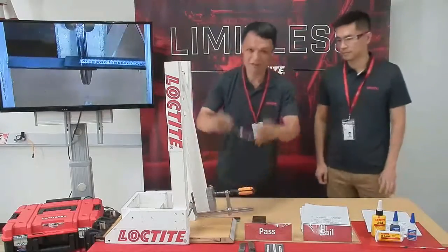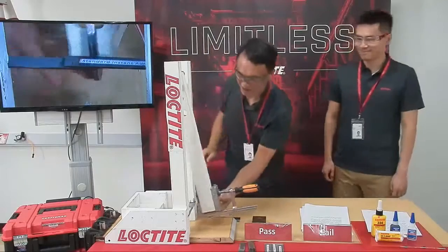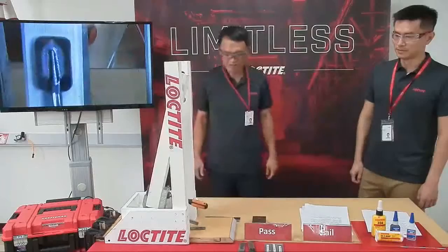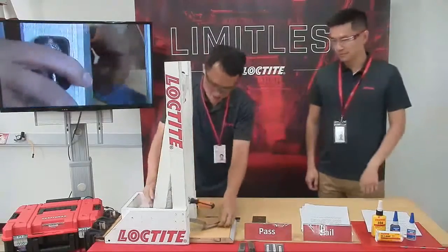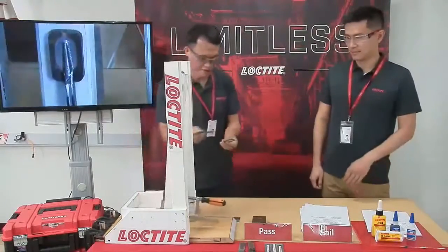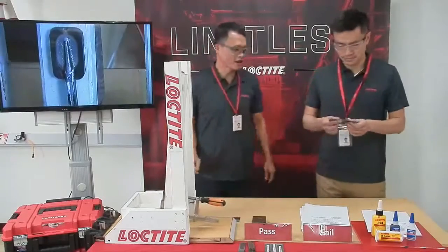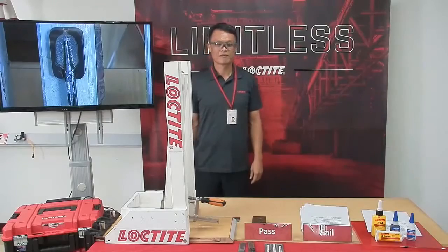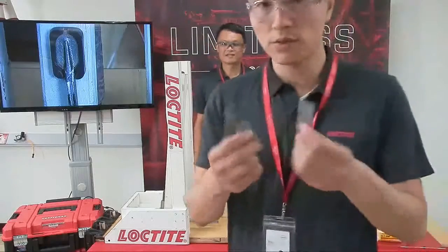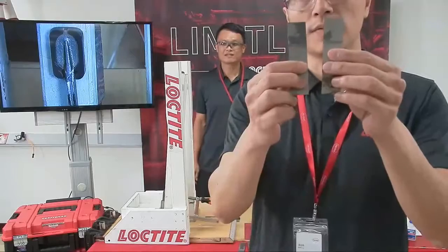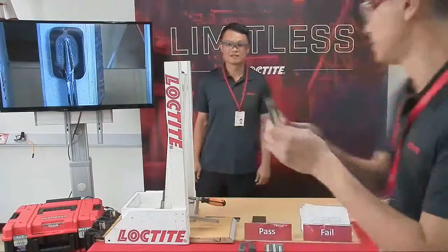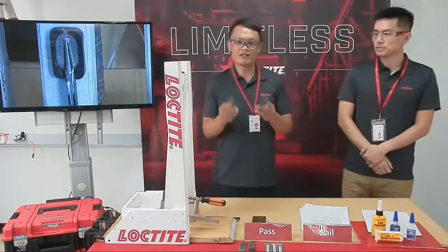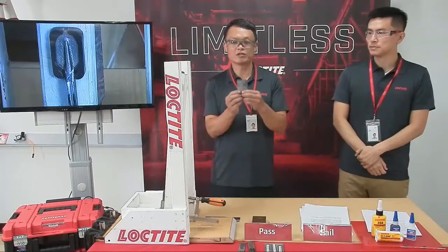Oh, sorry, I have to put on this one. It breaks immediately, but anyhow, we still want to have an inspection by Ken to see the failure mode here. Yeah, it's not surprising. It's separated, and you can see both sides have residues. So this is a very typical cohesive failure of the joint.